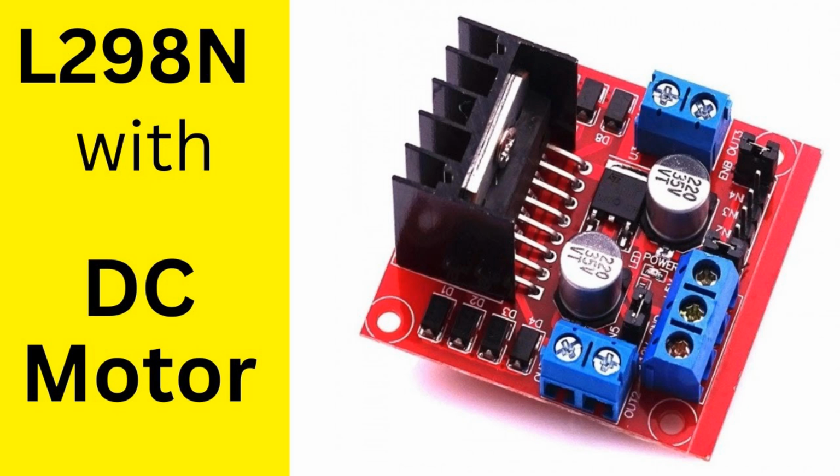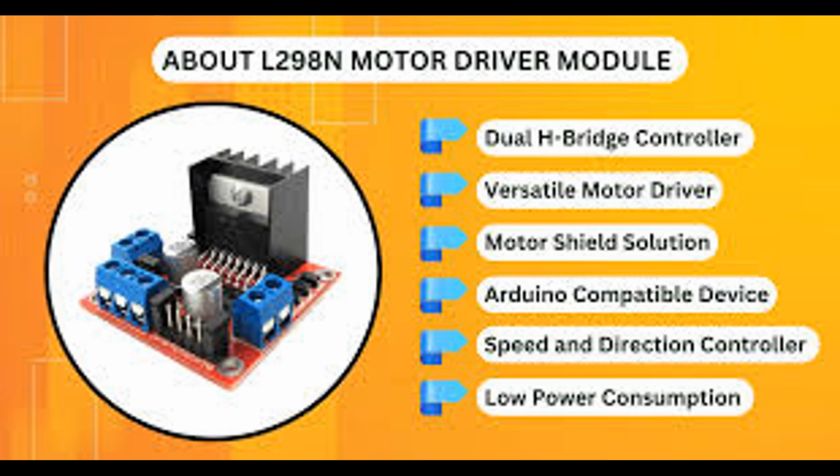5. Integrated BLDC motor drivers, motor plus driver. Function: these are integrated systems where the BLDC motor and the driver circuit are combined into a single unit. This simplifies installation and wiring for compact systems. Operation: the driver module and motor are often designed to work together, making them easier to configure and control. These integrated solutions may include sensors, such as Hall sensors or encoders, as well as additional features like thermal protection or current sensing. Advantages: easier to implement and compact.